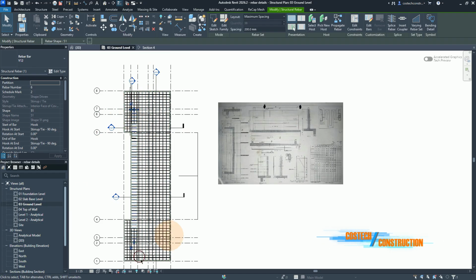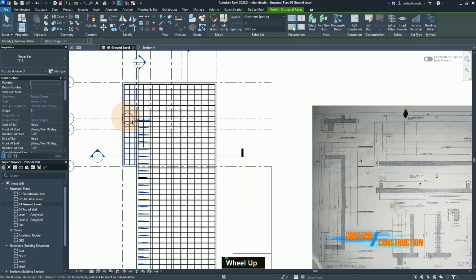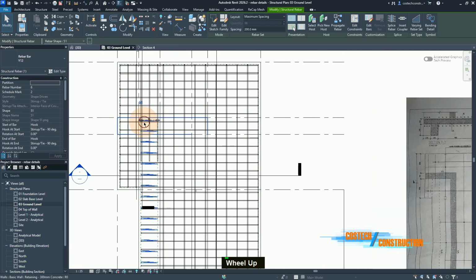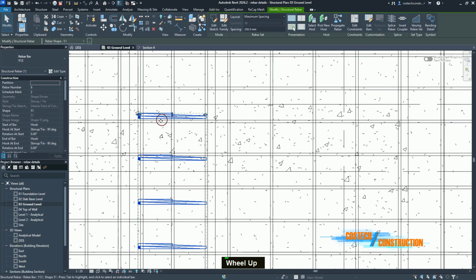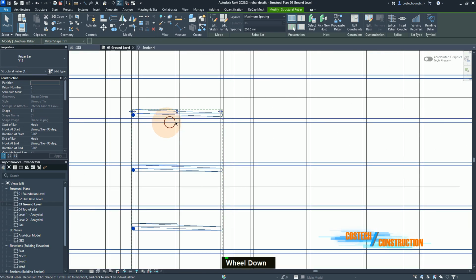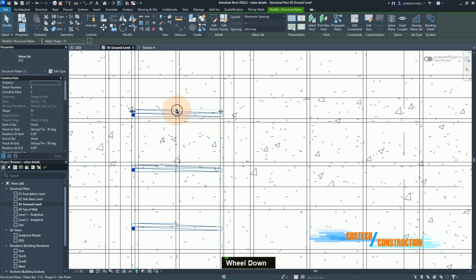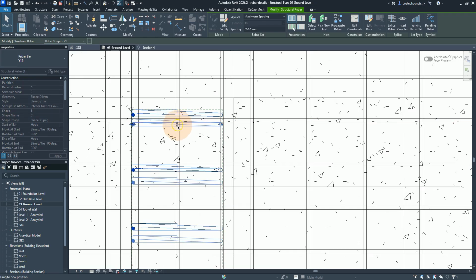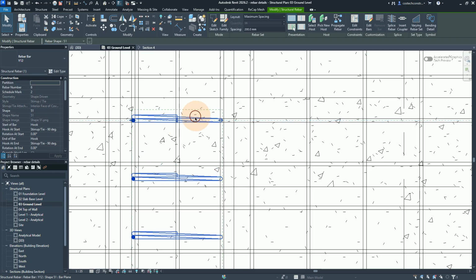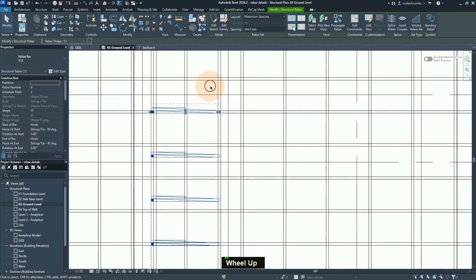we have the stirrups placed, and we can zoom so as to modify the stirrup position or span. So for this last rebar set, I will move it slightly up to this other one here. And I'll also go to the other side.